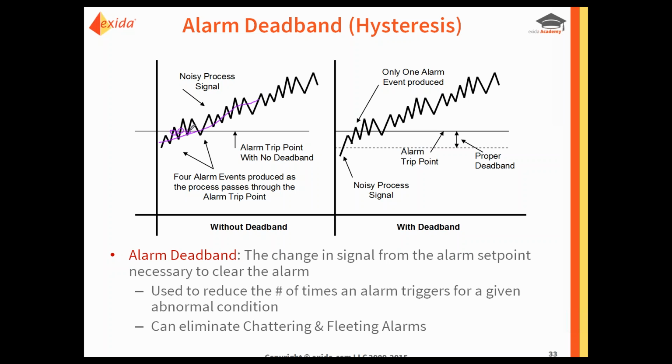So that's a nuisance alarm. That's actually a chattering alarm. To the operator, that could be quite annoying. They may ignore the alarm. Hopefully they won't, because they'll realize it's valid, but it will still be annoying because the alarm is occurring 4 times.